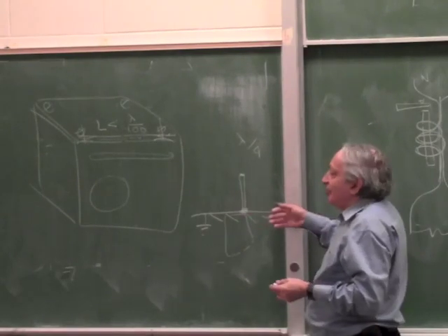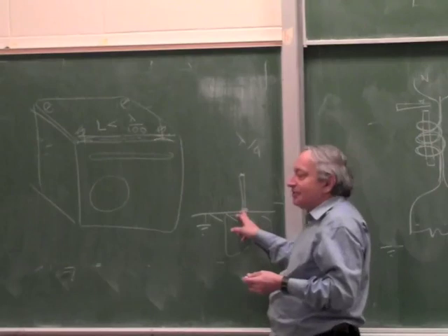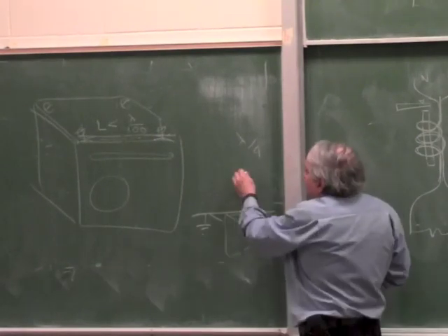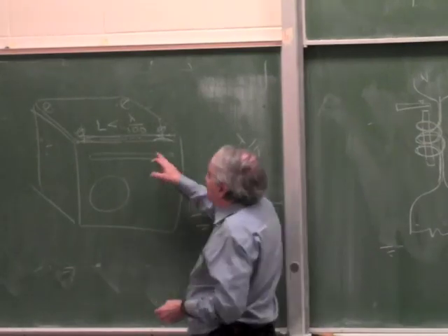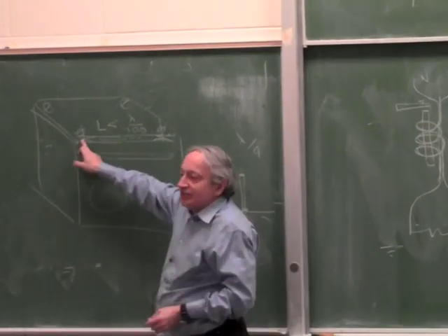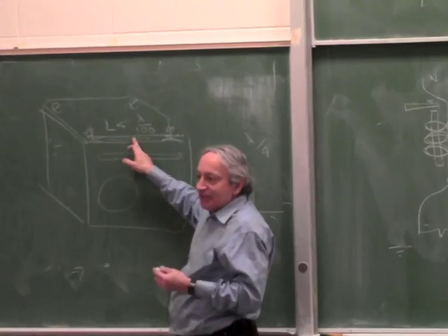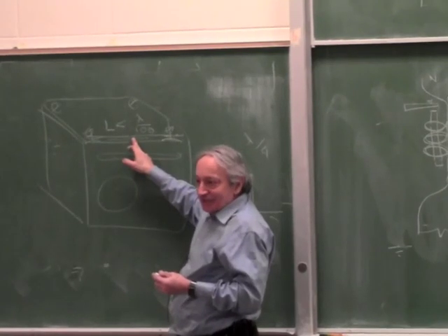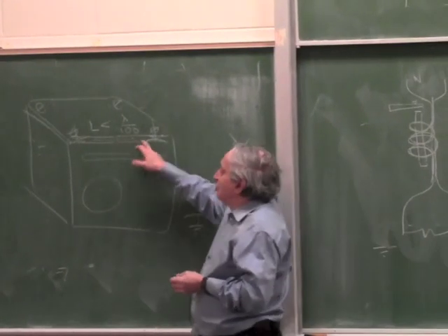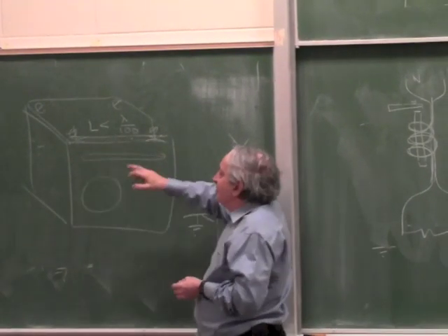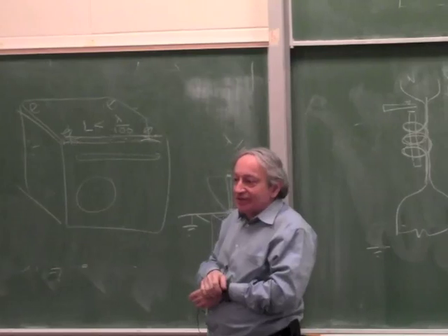So basically, when you deal with RF, if one end is grounded, it doesn't guarantee the other end is grounded, because you can have a standing wave. So because of this, if you have things like this, it's grounded here, it's grounded here, it doesn't guarantee the middle will appear grounded. Okay? So to make a shielded box, no openings, including slots in the cover, can be bigger than lambda over 100.